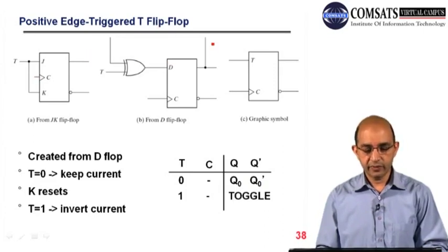So you will see that we will arrange or use a D flip-flop in such a way, by using some fundamental logic gate, that we can achieve the same toggle by having one input only. So here you can see we have an XOR gate, and the output of this XOR gate is fed back, and here we have T and this is the D flip-flop.